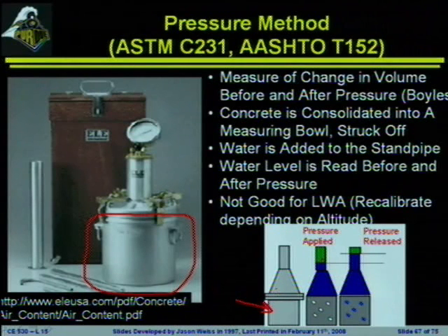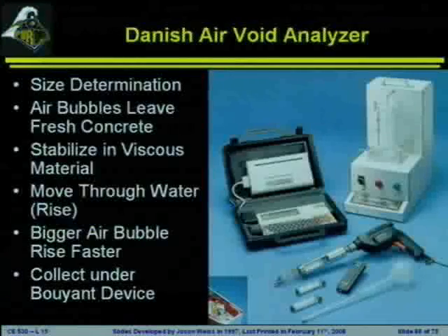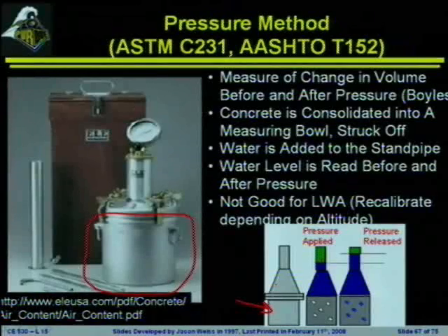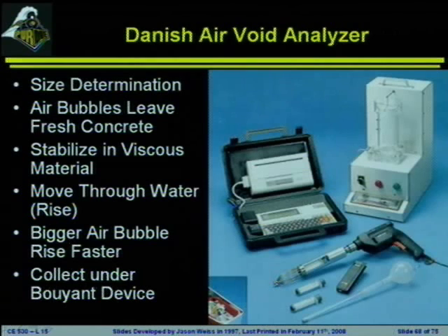Now, there is one big caution in using this test. You cannot use it when you've got porous aggregates. So if you've got something like a slag aggregate, or a lightweight aggregate, this test will not work very well. It also will not work very well at high altitudes because the pressure needs to be corrected. So you need to calibrate this particular method.